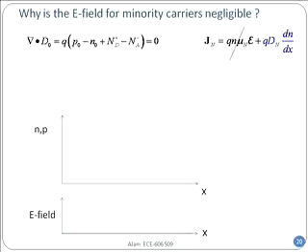So what's happening? You remember that in equilibrium, if it is a homogeneously doped sample, as was the case for the example I just told you about, in that case, the electric field will be zero, because N0 and P0 and Nd plus and Na minus, they will conspire together to make the electric field locally at every point equal to zero. So that was not a problem. Now, remember that this was an acceptor doped region, right? That's how we set up the problem. In an acceptor doped region, I can say that P0 is equal to Na, right? In equilibrium.